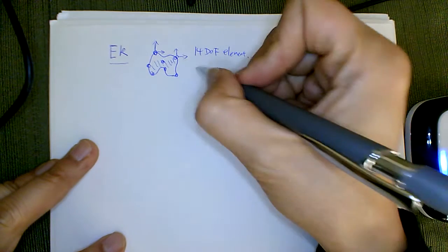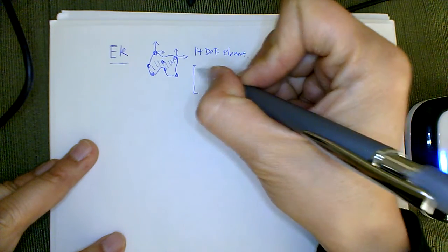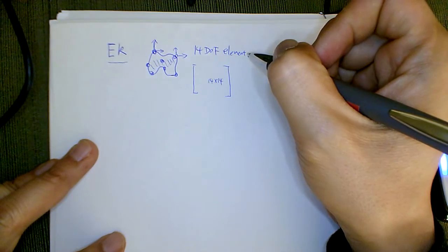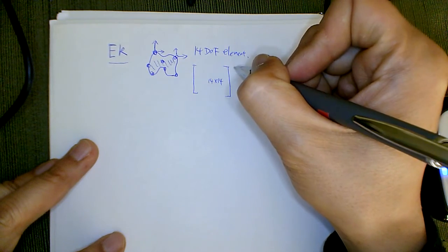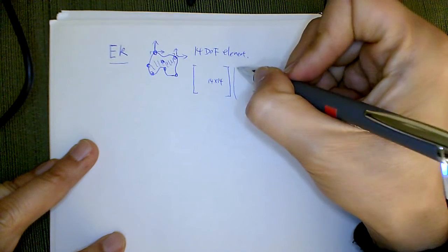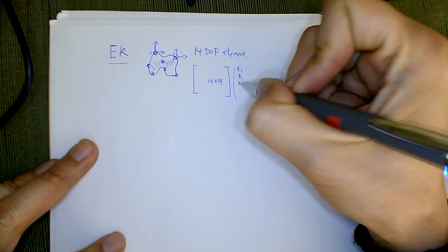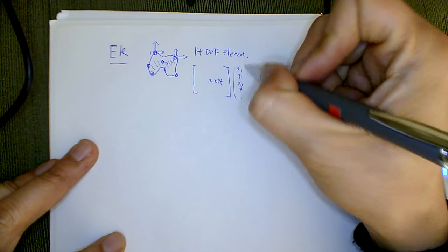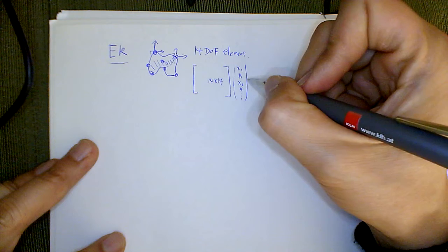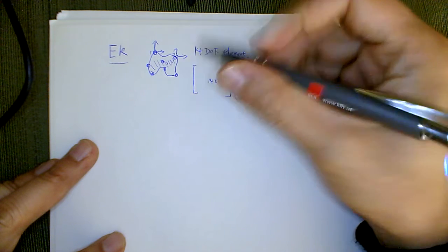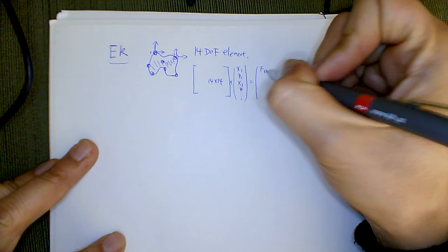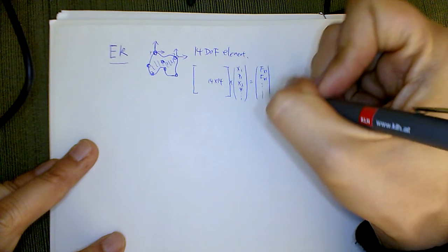And as a result, the EK will be a matrix that is 14 by 14, right? We talked about it. So how are you going to organize it? You organize it as x1, y1, x2, y2, something like that. And we know that if you multiply the stiffness matrix with displacement, you get a force: fx1, fy1, all that type of stuff.